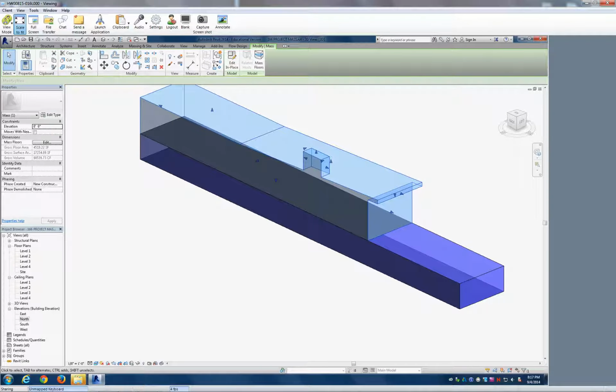We're not counting the outside here because it's not enclosed space. It's not going to be counted in the FAR, right? So even if it's a roof terrace, we're just looking for enclosed interior space. And FAR is measured to outside wall, right? So it'd be nice if it was inside wall, but might have to be if they want buildings to have more insulation and get thicker walls.